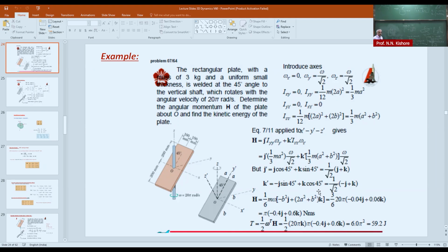this is in the matrix form. That's also there in the next slide. These inertia terms are with respect to the x prime, y prime, z prime axes, and we can find them very easily. They are all 1/12 ml square. Then about z prime, it is the sum of the x prime inertia plus the y prime inertia, and only the principal axes.